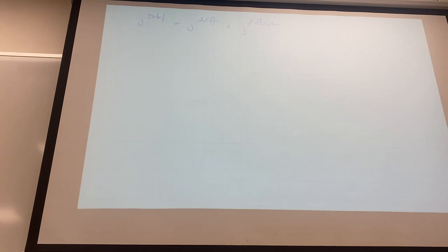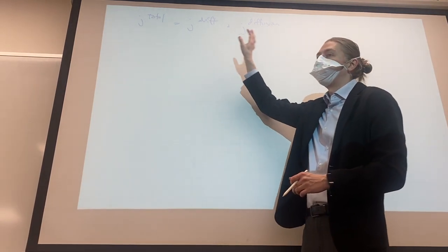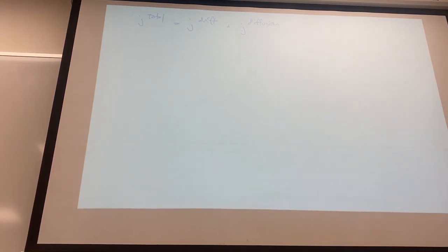And for the diodes that I passed out on the first day of class, current is not flowing through those, which means diffusion and drift have balanced, they're equal and opposite, and the J total must equal 0. And for a higher density of doping on one side or another, the number of carriers that have to diffuse out in order to reach that equilibrium will change. That changes the physical size of the area that is totally depleted of carriers. So if you have a really high density of dopants on one side and a low density of dopants on the other, the low density side has to give up more physical space. This region that has stood up this electric field is larger on the lightly doped side because you need more volume of the doped semiconductor in order to compensate for the same number of atoms on the other side.